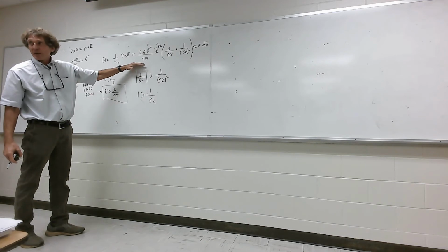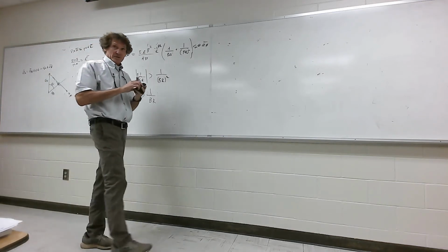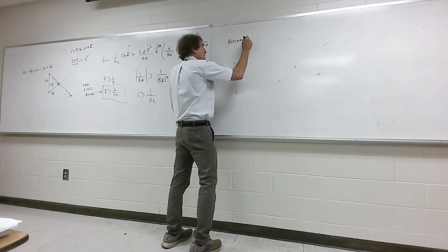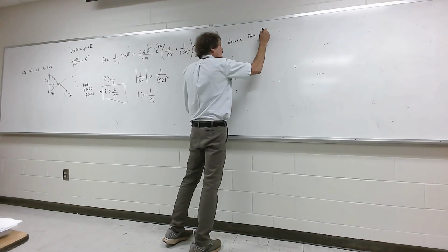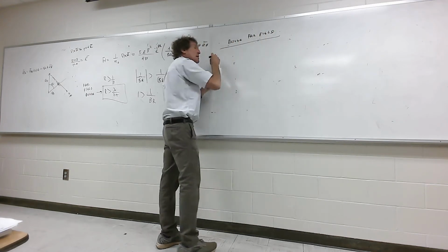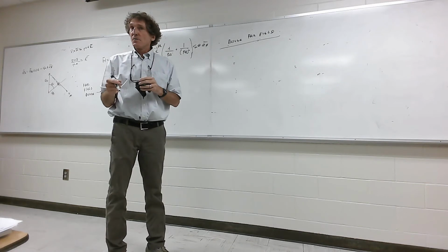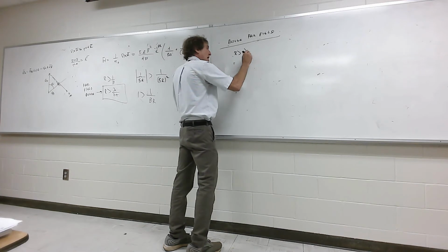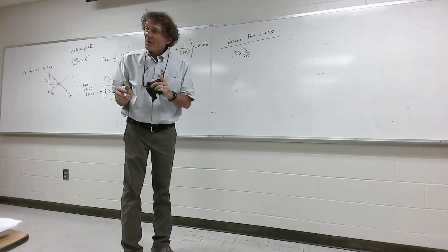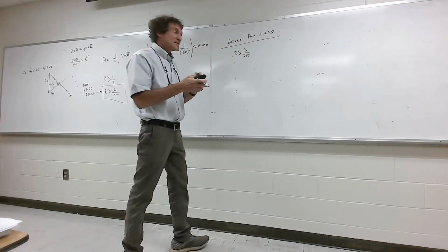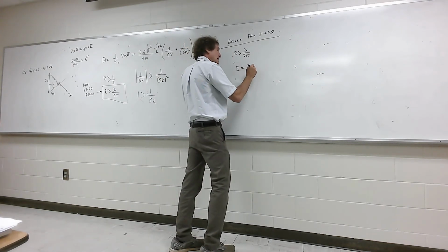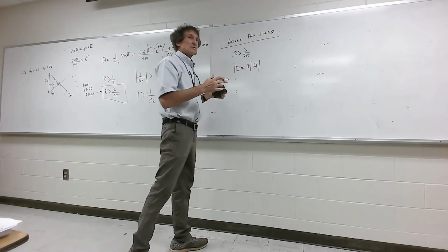Here's what we normally do here. We say we're going to assume far field. Got it? So I'm going to write it down. We're assuming we're in the far field. Okay, then what we do is this. That means we're assuming we're at r greater than lambda over 2 pi. And then in the far field, there is a beautiful relationship, and that is that the E field is simply equal to eta times the H field in terms of its magnitude. Now there is a correction for orientation.